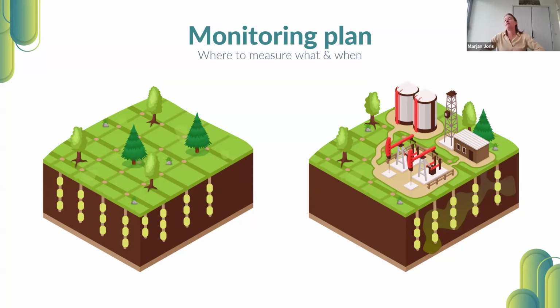If you don't have any information up front, then the only solution is to measure everywhere at different locations, in a raster, for example, at different depths, different locations, to have any idea about mass flux and mass discharge. But of course, most of the time information is already available, and it will definitely help to set up a monitoring plan to evaluate this available information. For example, you can already select to measure near the locations of the contamination, downstream from the contamination, etc.